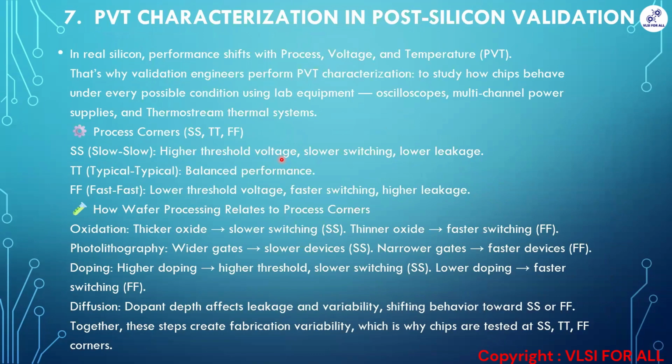So mostly which oscilloscope will be used in the industry? 25 gigahertz bandwidth oscilloscope, Keysight. Because the oscilloscope can accommodate low speed and high speed peripherals, right? A 25 gigahertz bandwidth oscilloscope is very high. That can be used for low speed peripherals like I2C, SPI, JTAG and high speed peripherals like PCI, SGMII, Aurora. So from the industry standard point of view, they'll use a 25 gigahertz oscilloscope.